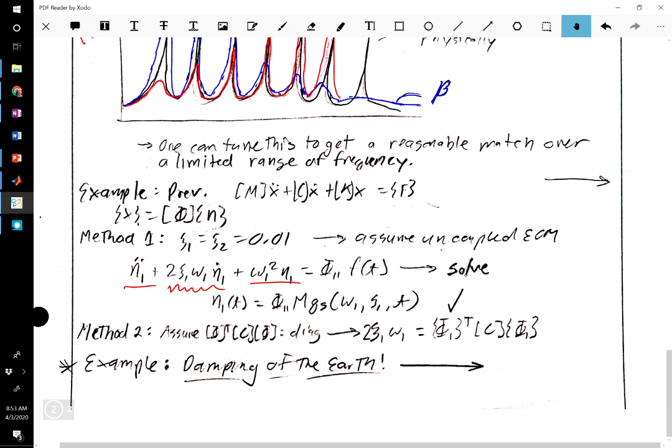And so where before we used the real form, now we might have to use the damped form, which was the real part of a e to the lambda t, where lambda is negative zeta omega n plus i omega d. So we can use one of those forms for the solution. Okay, so this is how we handle multi-degree of freedom systems with damping.